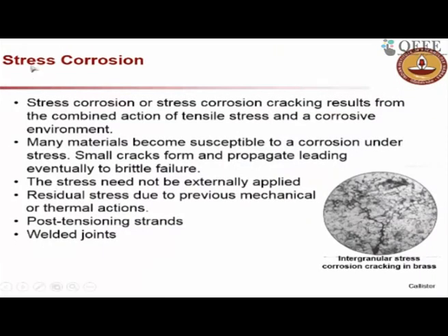Now there is one more mechanism, which is stress induced corrosion, and this is one of the issues we may face in pre-stressed concrete structures, because we have steel cables which are under stress in pre-stressed concrete. If you apply too much stress, you may have a problem like that. So we have to be careful not to over stress the steel, okay.